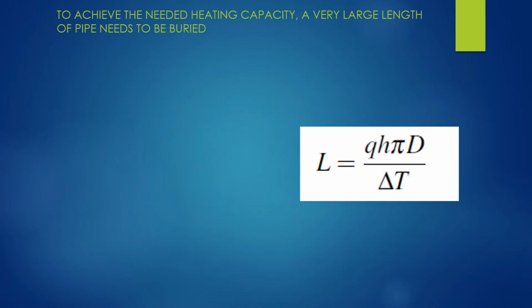We found that at depths where the temperature difference was within 10 degrees, enormous amounts of pipe would be needed, but as we dropped the pressure of the refrigerant and thereby increased that temperature difference, we could cut down those lengths of pipe by entire orders of magnitude. So it turned out that the temperature difference made the biggest difference in the amount of pipe that you need to bury, which in our case we gained with a lower pressure of the refrigerant.